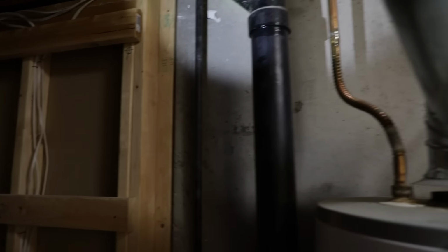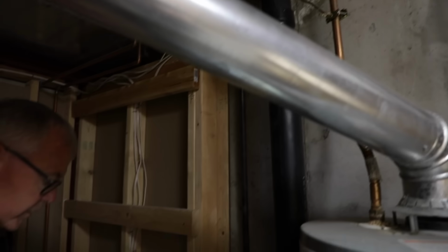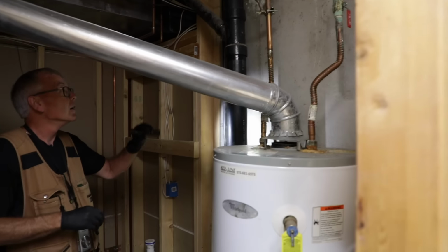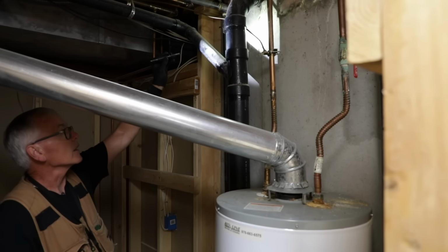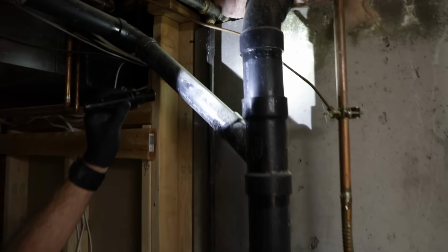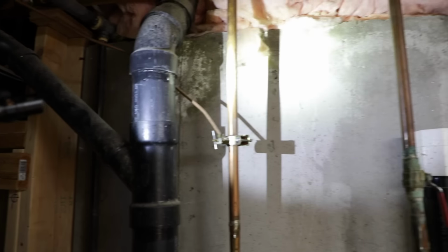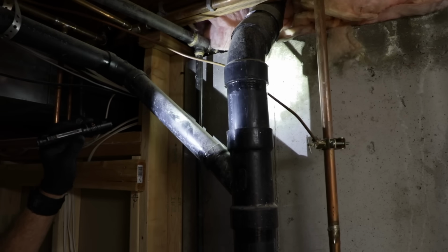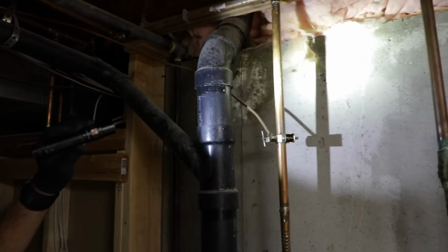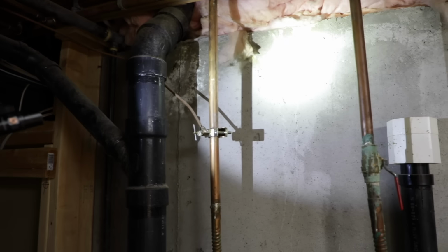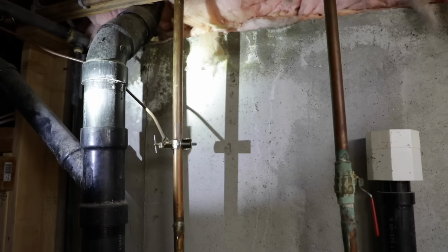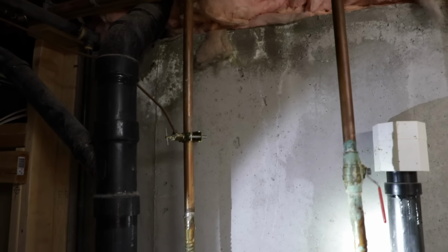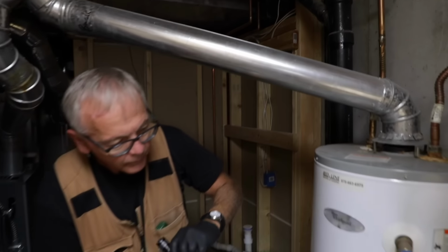So I'm going to begin to look to see if I have any cracking or any other issues. I do see I've got a little bit of efflorescence up here, which can signify that I've had some past moisture intrusion. So I'm going to note that in my report. We don't know what the source is, but we can certainly describe that it's here and where the location is on the foundation wall. So we keep on moving down.